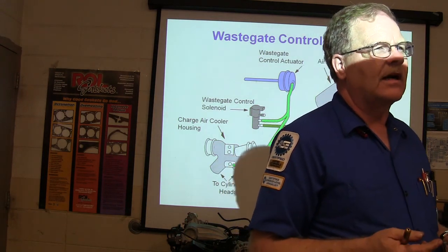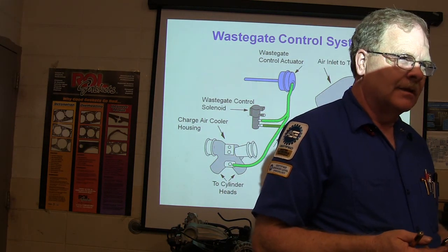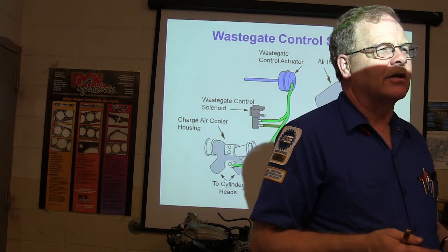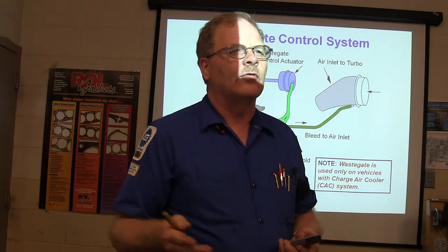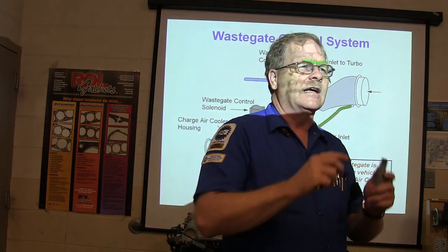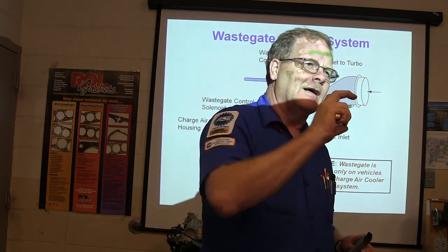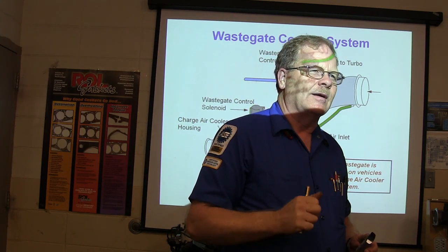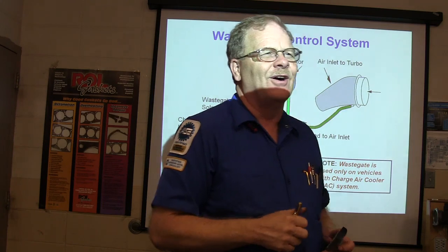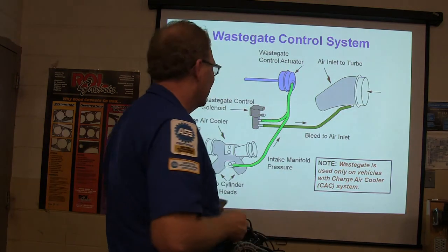Because when you compress air, it gets hot, right? When it gets hot, there's less molecules of oxygen in a cubic inch of air. So you want to cool that off before you put it in there. It actually gives you more power. So they got these big old hoses. If any of these clamps on these big old hoses gets loose when that turbocharger is putting pressure through them, it'll make whistling noises, and we just have to work on that.